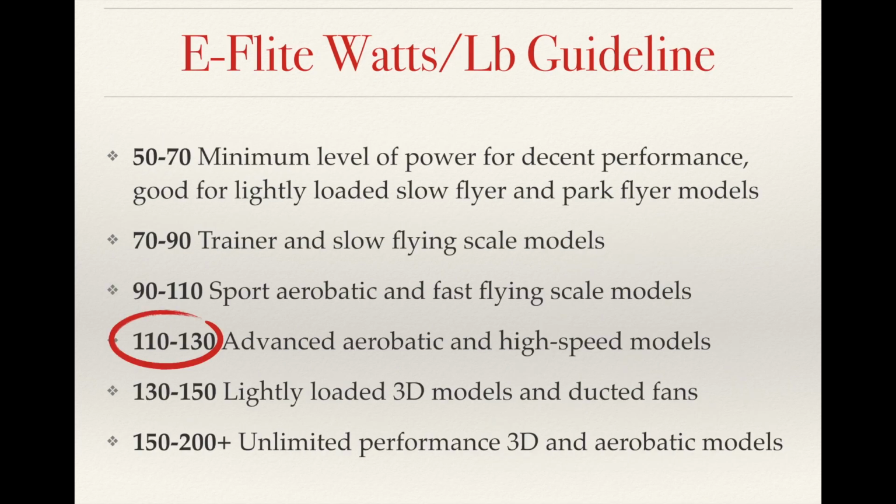Okay, the other thing I wanted to do a quick review on is this watts per pound guideline that E-flite put out. I stumbled onto this a couple years ago, and it's really good. If you're really heavy into flying and you're a real geek about it, you may have a completely different point of view. But if you're new and you're not exactly sure where to start, this chart is a really decent place to get an understanding of where you need to configure your airplane to fly. For a lot of my planes, I like this 110 to 130 watts per pound number for the type of flying that I like to do.